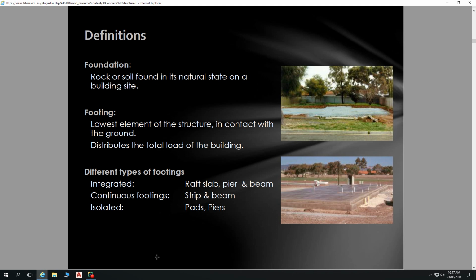But we've got those areas that are not as bad as they come. They're not super worse, but in those old cottages you get a lot of movement, massive cracks and things happening there. And the big difference is the type of footings used in those older cottages, which are just strips. They might be big slabs of bluestone or some concrete, but they're footings which are simply a strip rather than a raft slab. Whereas later on in construction, the invention of the raft slab has enabled us to build in places like Newton and Ross Trevor without having significant issues.